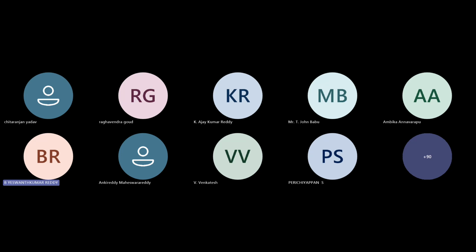Sir, one more thing. Other than melting point, what desired properties should that material have in order to go for printing? Let me tell you one example. In the market, there are two types of polycaprolactone. The first has molecular weight 80,000, and the second has molecular weight 40,000. I tried with both. When I tried to print with the 40,000 molecular weight PCL, I was able to print the first layer.